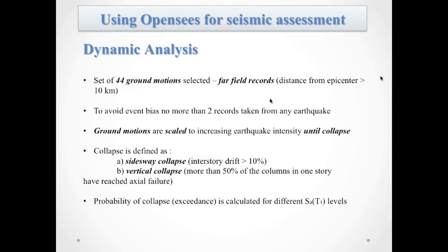But practically, I would say that after 6 or 7%, the IDA curves are practically flat. So that number really doesn't matter. It's a big number, but it's selected so that we are sure that the IDA curves are in their flat plateau. When the curves are in this plateau, it means that the structure practically has no resistance.